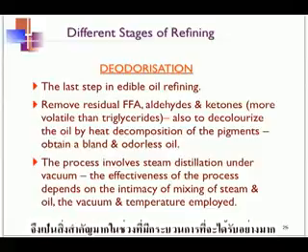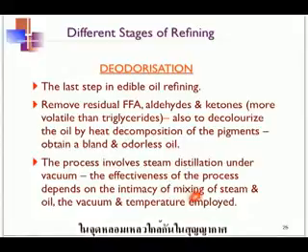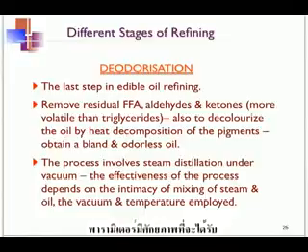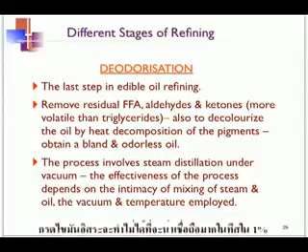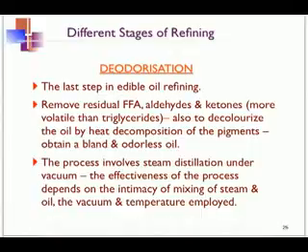So it is very important during this process to get a very intimate mixing of the steam and the oil, as well as the vacuum and the temperature. The control of these parameters is important to get an efficient deodorization, to remove the free fatty acid down to a very low level, less than 0.01%.